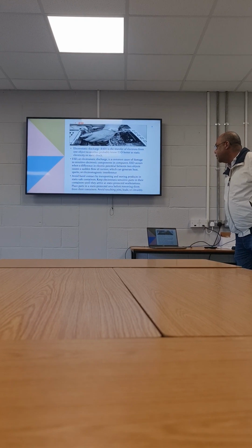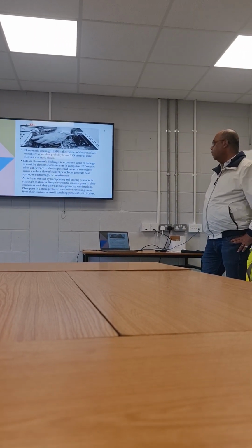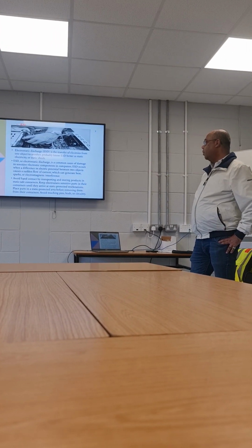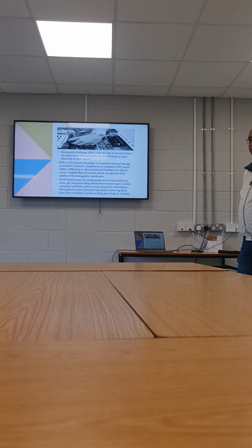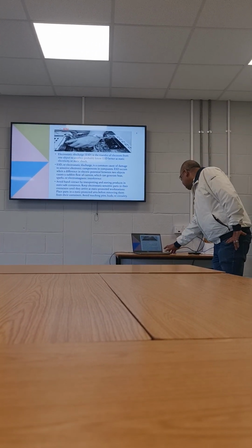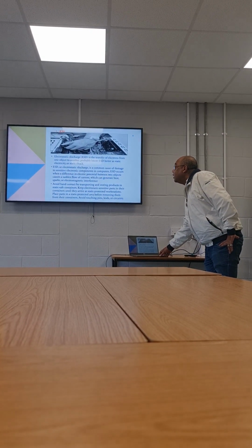Place the parts in a static protected area before removing them from their container. Avoid touching pins, leads, or circuits. So there you go, that's the ESD.